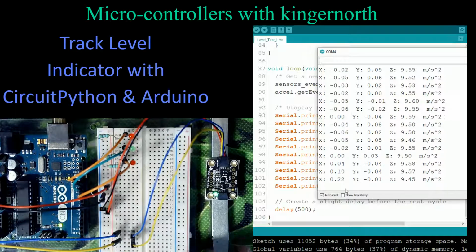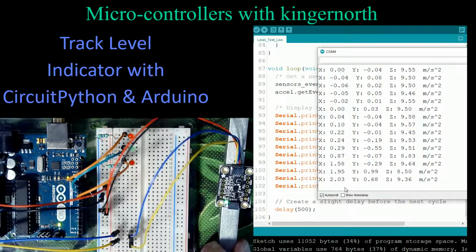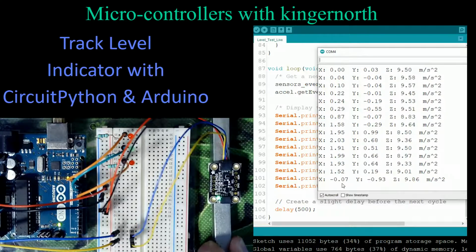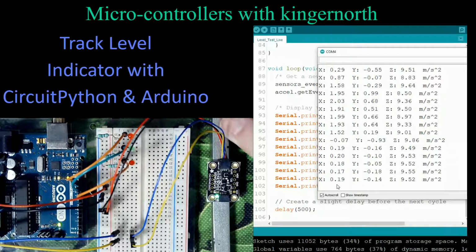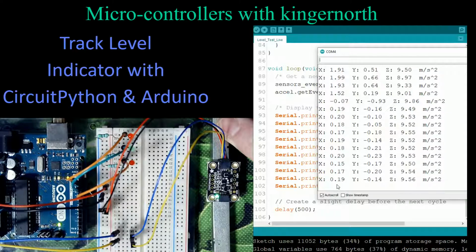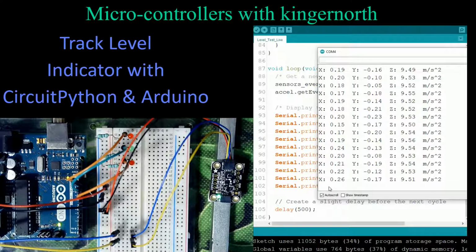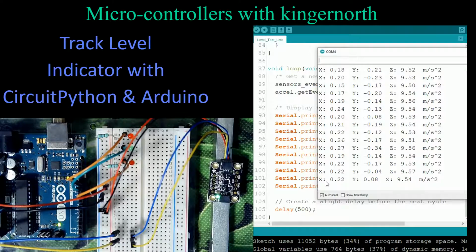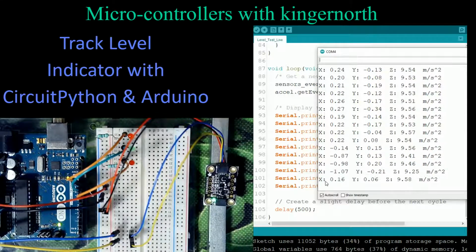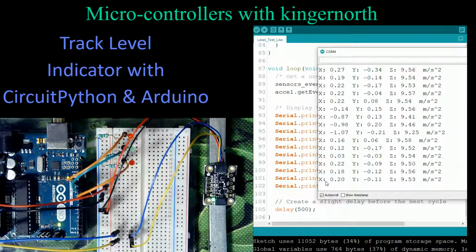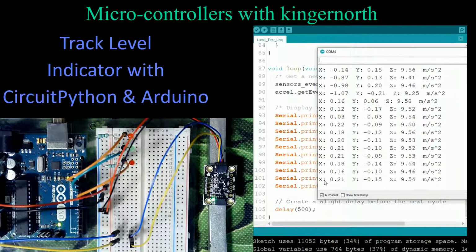And if I let it sit, I can tilt it the other way, and we can still see the numbers get larger. So when I lift this end, the far end, the top of it, the numbers go positive. When I lift the end closest to the bottom of the screen, this end, the numbers go negative. So we can see that we can go off center. It's actually measuring whether we're level or not. Ideally, level is 0. And as you can see, just sitting there, it's also getting some various readings. It changes from about 17 to 20. I saw 21 go by there, but that's about the range.